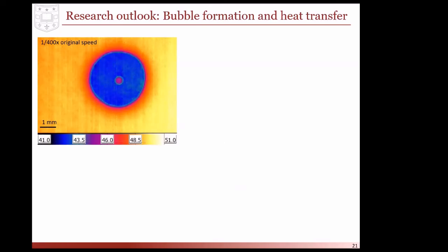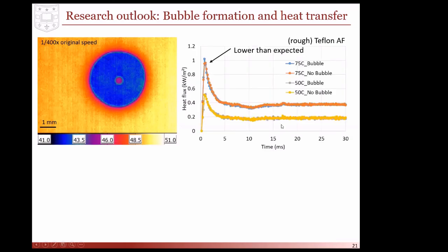Where it is critical, though, is if you're talking not about cooling applications, but the inverse, where, for example, you're thinking about icing, or even more importantly, inkjet printing or additive manufacturing, for example, with metal or with polymers, where you do not want a central bubble that has a different cooling rate or phase change rate eventually than the surrounding droplet, because that would create sites where you create defects. So we want to be able to mitigate this effect of the central bubble where we see a very different heat transfer rate.